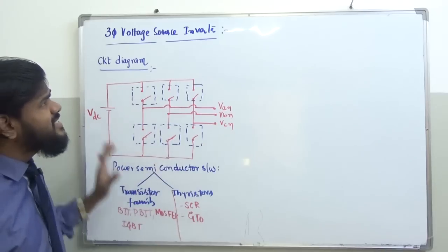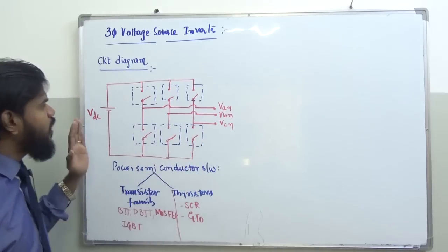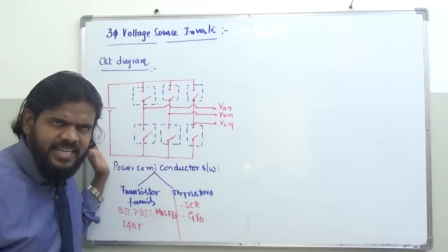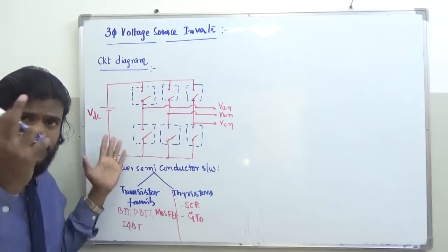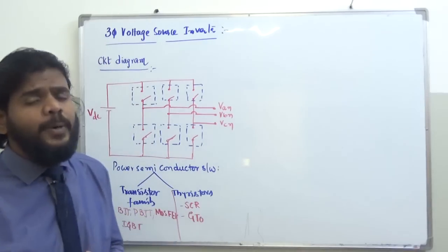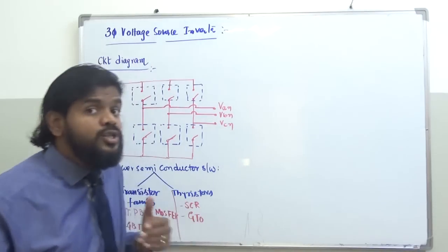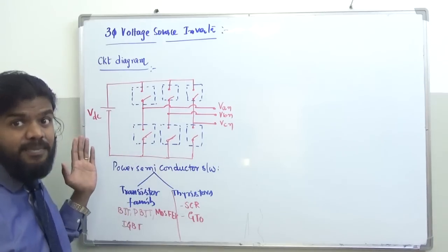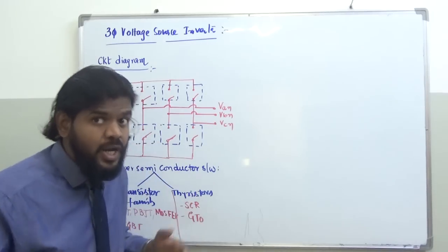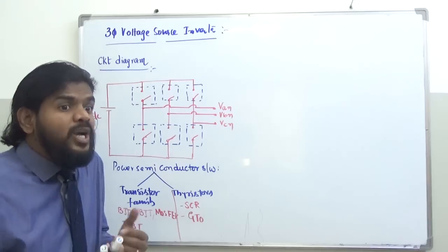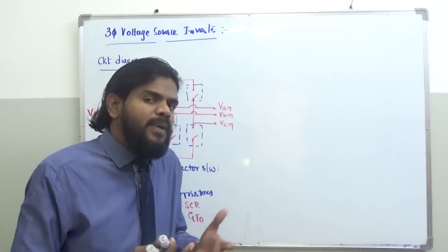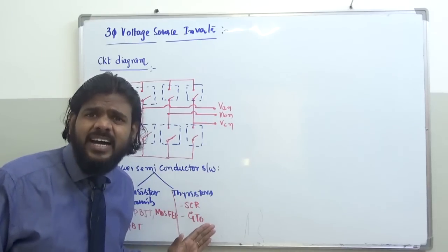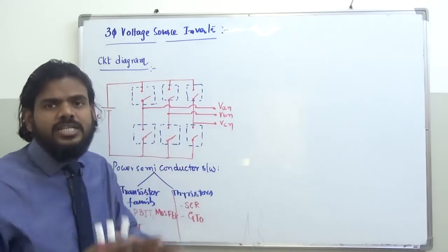But here in a DC to AC converter discussion, you find a DC supply, a battery, as the input, right? When you have a battery input, you find the battery voltage continuous with respect to time. It doesn't get to zero at any point of time. So there is no possibility of having a negative voltage or a zero voltage in the supply. Because the supply is not going negative and not getting to zero value, we can never turn off an SCR with the arrangement as it is.